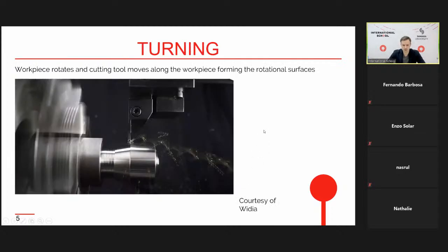Okay. The first example is a turning process, and here you can see a cutting tool, not only the cutting part. This cutting tool is black because it has a different layer of coating relative to the previous picture, so it's normal for a cutting tool. And we have a tool holder for clamping and holding the cutting part of the tool. And also we have an adapter to put this tool holder and tool into the machine, which provides the cutting process and the movements of the cutting tool and the workpiece relative to each other.